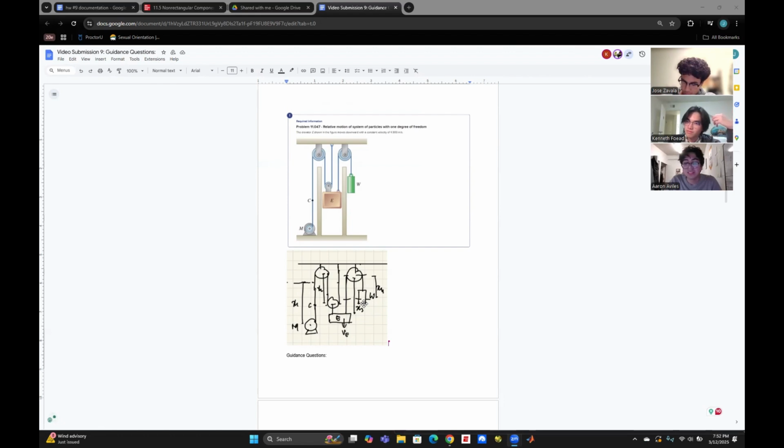That's how you know that C moves 2 times as much. So you can use that work energy theorem because there's 2T on E from the left-hand side pulley system. Because the work has to be the same, the displacement is double, which means that as E moves, C has to move double.